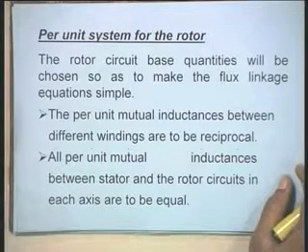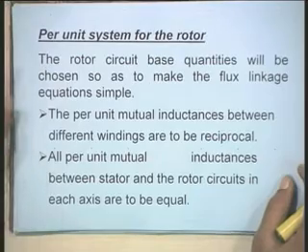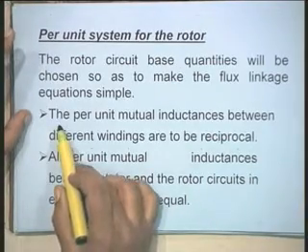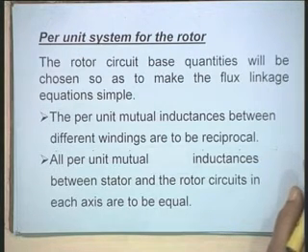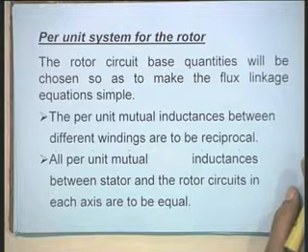Okay. Now, the primary consideration for choosing the base quantities in the rotor is to simplify the flux linkage equations, to make this flux linkage equation as simple as possible. One way of simplifying these is that we make mutual inductances between different windings reciprocal.